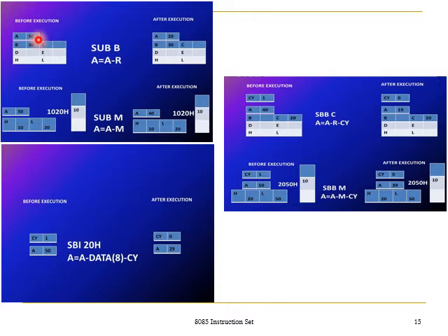For any arithmetic or logical operation, the first data will come from the accumulator and the second data will be from the specified register or memory. You note this, right? So the first data will be from the accumulator and the second data will be from the specified register, B register here. So 50 minus 30 is 20, and that is stored in the accumulator after the execution of this instruction.